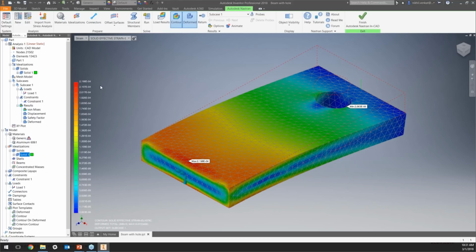I know that when I first started doing simulation, almost 6 or 7 years ago, I was just like, man, I've got a really awesome computer. Let me just make the mesh size infinitesimally small and run this thing for like 16 hours. And then you get an answer that's maybe 0.5% better than the one that took you 30 minutes. It's not worth it. Yeah. So definitely something to keep note of. Where to stop refining your mesh. Yep. At what point you hit that barrier, you've hit that convergence. Yeah. So definitely keep that in mind.